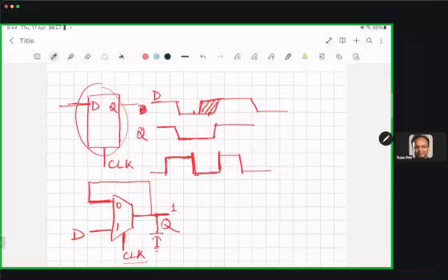If you charge a capacitor to the highest voltage it can reach and then remove the source, gradually the charge will discharge, because these capacitors are not ideal. They will have some resistance across them. You are all aware of the RC time constant, right? The time required for this discharge is proportional to R and C values. So it will eventually discharge.